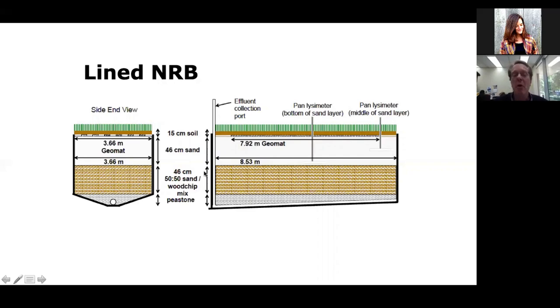So in terms of depth requirements for these systems, you've got, call it conservatively, 3 feet of topsoil and sand, and then you have your pipe, and that has to go on a gradient down to final disposal, which can be either a leaching galley or a concentric leaching pool. Depending on the space in the site, you could use a 4-foot galley, and underneath that, you need 3 feet before you get to groundwater, so that would be 10 feet. Or if you had the space, you could use 2-foot galleys, and then you would only need 8-foot depth to groundwater.